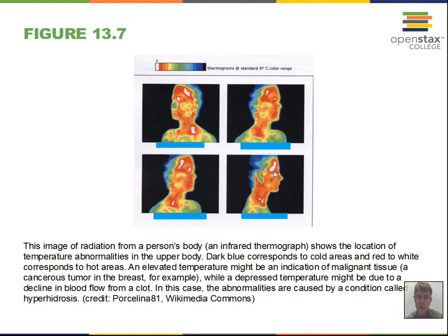This infrared photography is also used by utility companies to tell homeowners where they need more insulation. Photograph the roof of a home from aerial photography, and the roofs that glow brightly are too warm and need more insulation to prevent, in the wintertime, warm air going up to the roof.